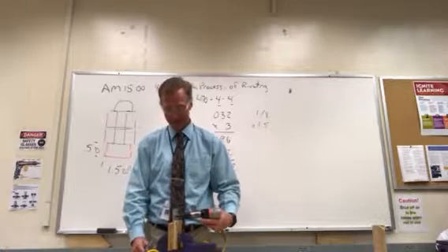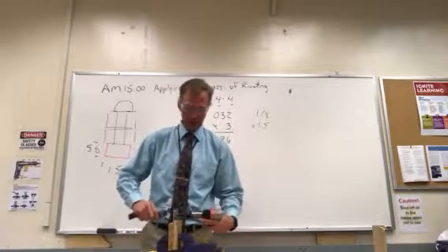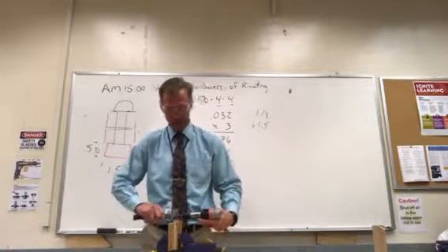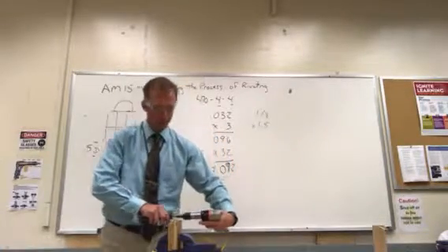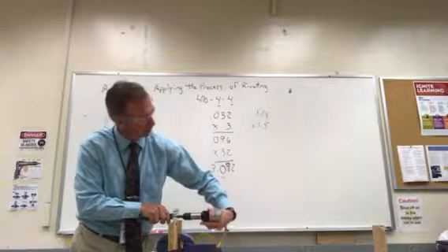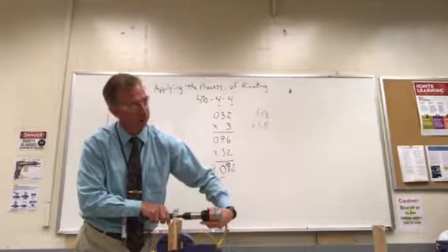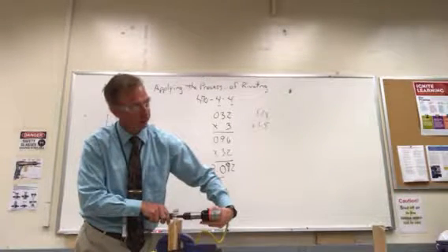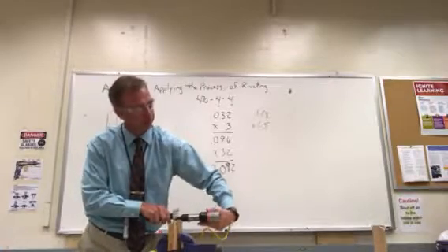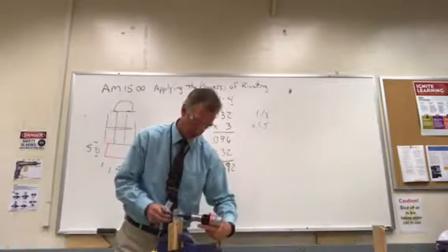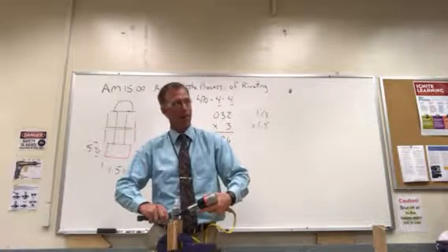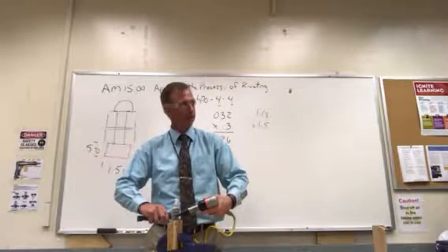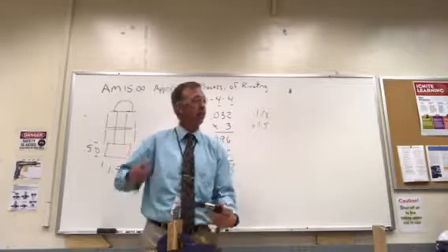So if I'm holding this like this, I've got to be square to it, right? Yes. What if I'm just trying to buck it like this or rivet it like this? Is it still going to do it? What do we have a chance of? Slipping from one side to the other side. Okay. So what happens if I tip it up from one side? You're going to dent the rivet. Okay, it's going to dent the rivet.